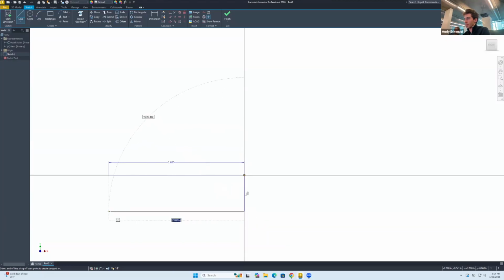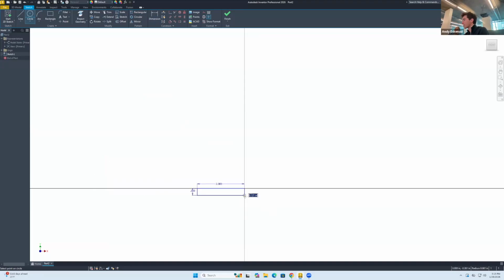So we're going to make a screw. Wait. Just Control Z. So I'm just making the body in the sense that we're going to revolve that. So you can imagine this is the axis of our screw. And there's a reason why we're doing it in this particular way. I'll explain in a moment. It's because that's what will allow us to use the coil command.